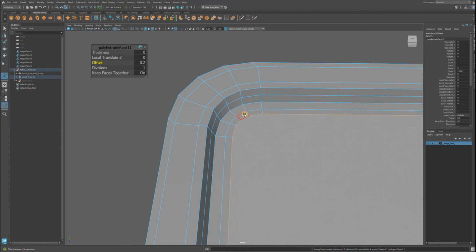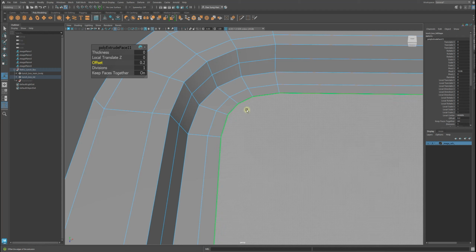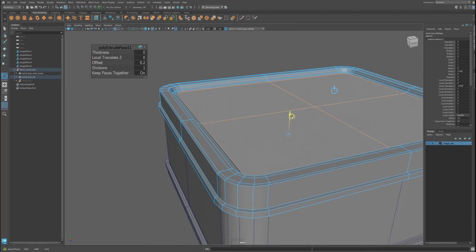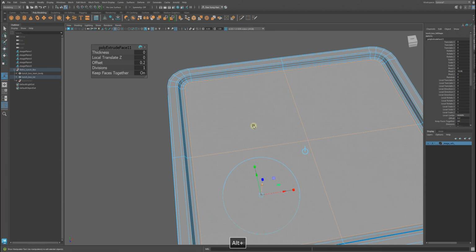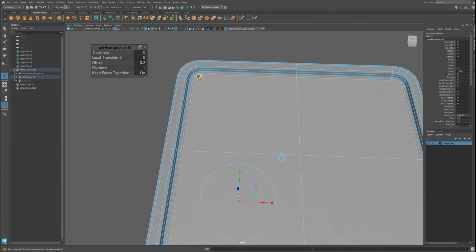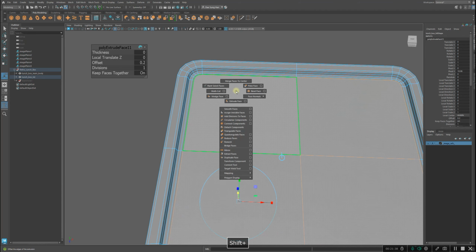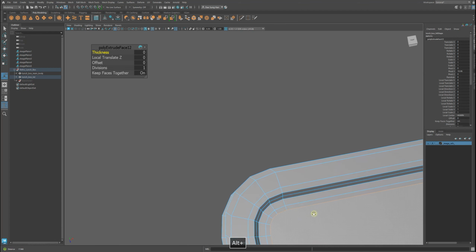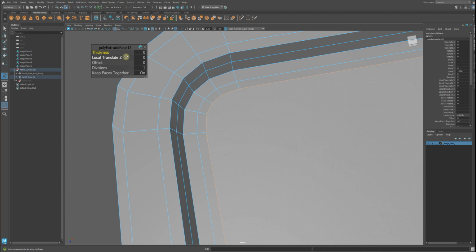So here and here, right? Maybe I need one more just to make sure. Because if I do that, right? I'm gonna do one more. So I have it selected, right? If I push or pull, that's not what I want. I just want to make another layer of a footprint. Shift right click and hold, extrude face. I did that, right? Watch carefully. Offset 0.1.